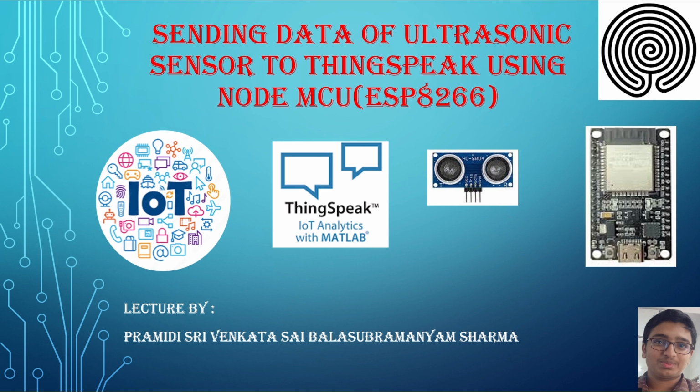And what data am I going to send? Why do we actually use an ultrasonic sensor? For distance measurement, right? So for distance, I will take one field, and one more for duration. We get distance by calculating with respect to duration, and duration is obtained due to echo. What do we mean by echo? Sound. Here we consider the speed of sound in air and use the formula for calculating the entire distance.